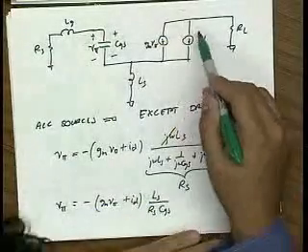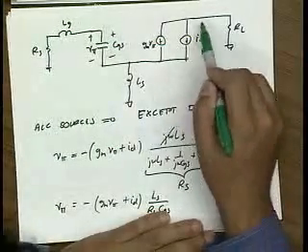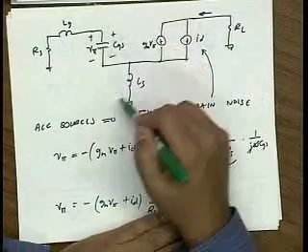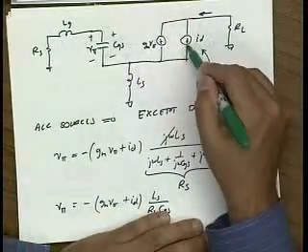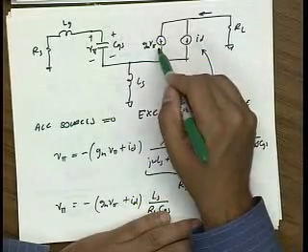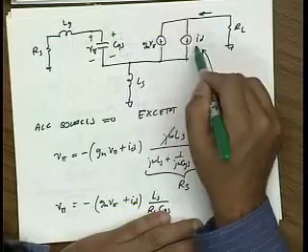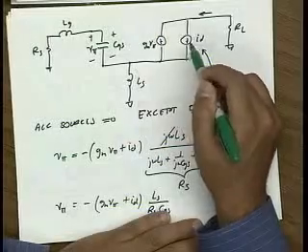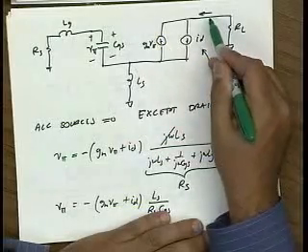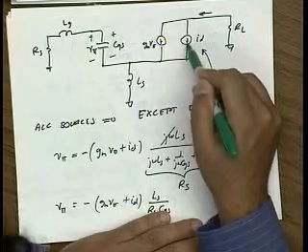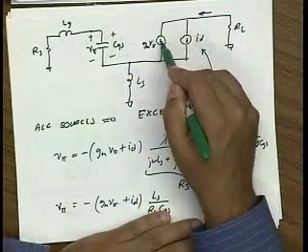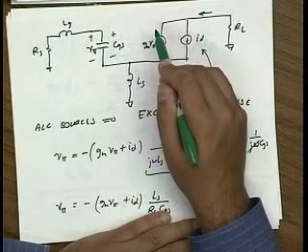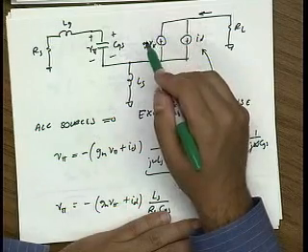The idea is that if I have one noise source here, and I'm interested in knowing the total noise drawn into my load, what I've shown in this calculation is that if I assume that this is a deterministic current, then this current, as a deterministic quantity, is always half of this current pushing in the opposite direction. So it would cancel it out, right? Now if I'm interested in the statistics of this signal, I know that no matter what, at any instant of time, whatever this current is, it is completely correlated with this current, and it's in the opposite direction. Does that make sense? Yeah.